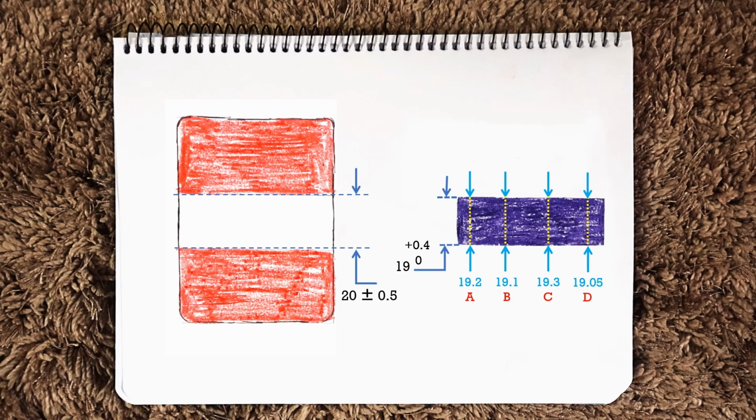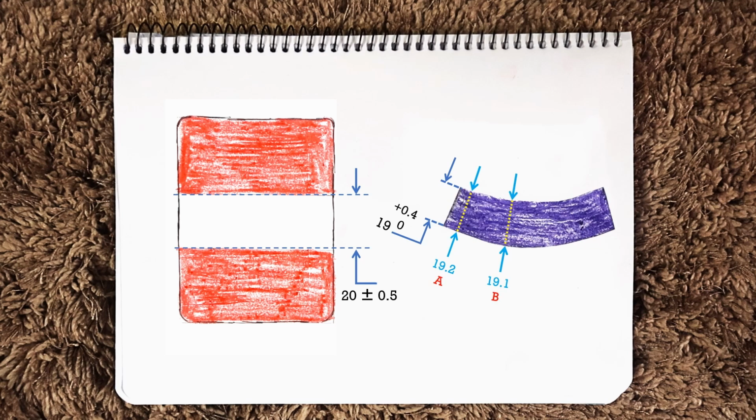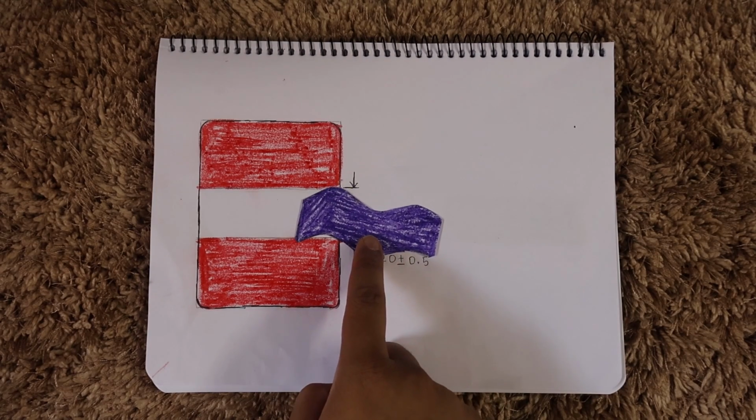Means the vernier caliper measurement will pass this part. With a vernier caliper, we cannot prove that this part is rejected or bad, but the shaft may or may not be assembled, depending on how much the part is bent or deformed from its perfect shape. So how can we confirm that this shaft will definitely be assembled?